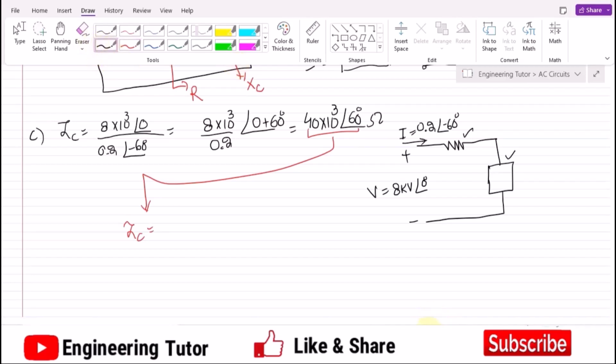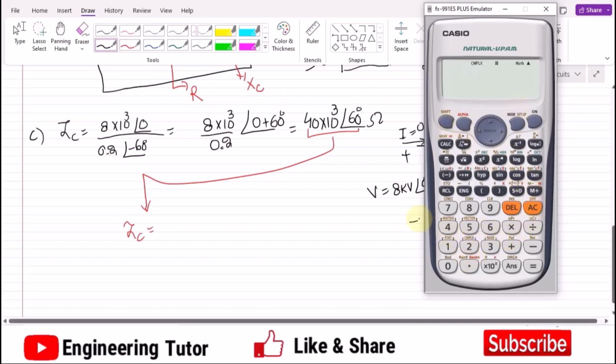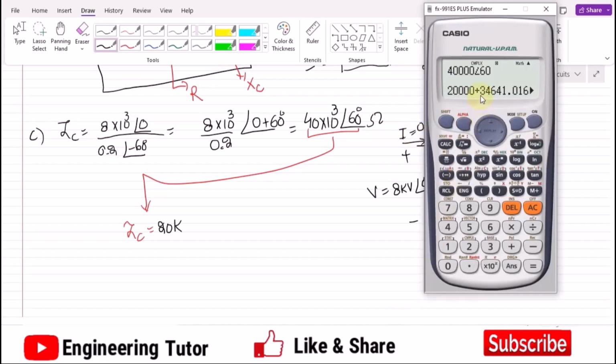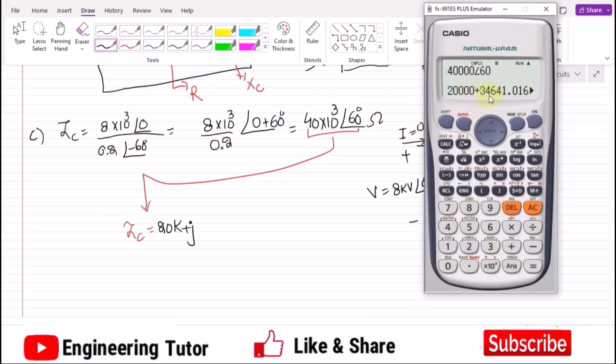Okay, so how to do it, I have been doing it by this calculator. So again writing 40,000, that is 40 1 2 3, and the angle with it is 60 degrees. So now pressing equal, and here I will get 20,000 or 20k, and the other quantity with it is plus j 34.641.